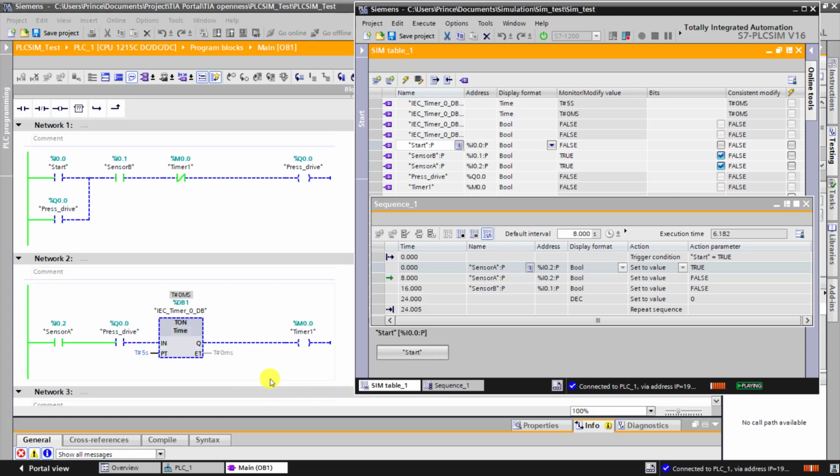The timer is done, and then our sequence moves to the sequence that is B. Wait for 8 seconds and then deactivate the sensor B. Great. Now we can see that the rest were done automatically. Now I move back to our simulator and then activate that a new material has been placed, and then press the start push button again for the sequence to start automatically again.